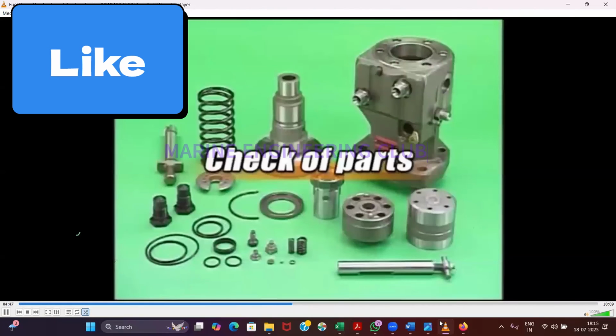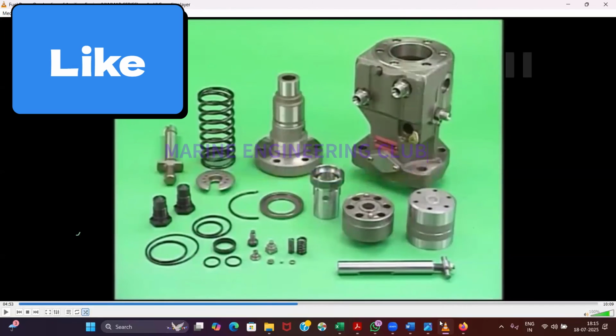So these are all the parts inside it. Do the normal checks: that there is no broken tooth on your control sleeve or on your rack, and if there are too many scratch marks on your plunger guide, then you have to replace it. On the delivery valve, sometimes you will see the top head of your non-return valve leaks a little. That means you have to replace your delivery valves at that point of time. And deflectors I've already discussed. Check the deflectors; if they are not in good condition we can replace them.